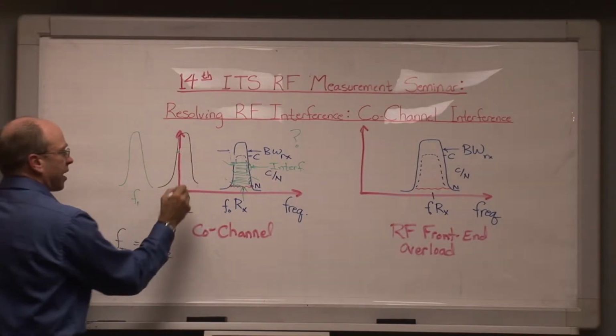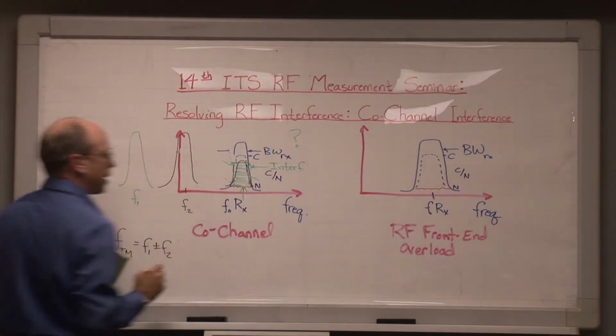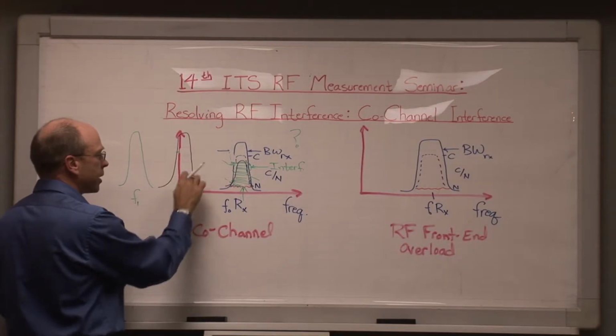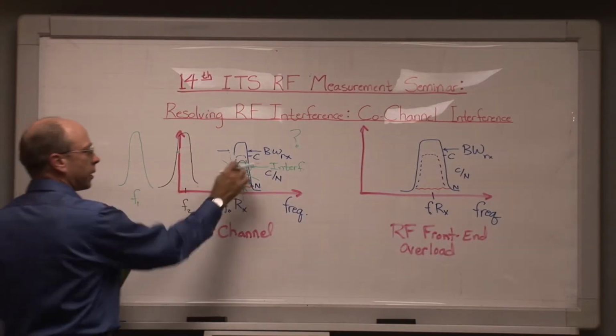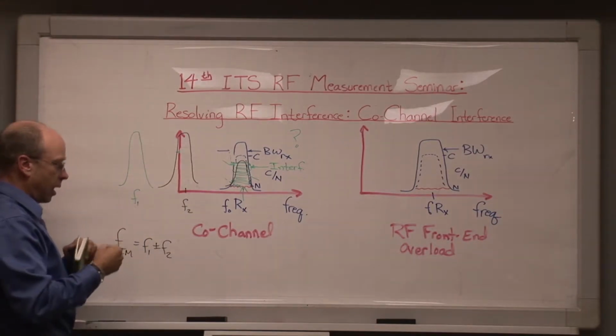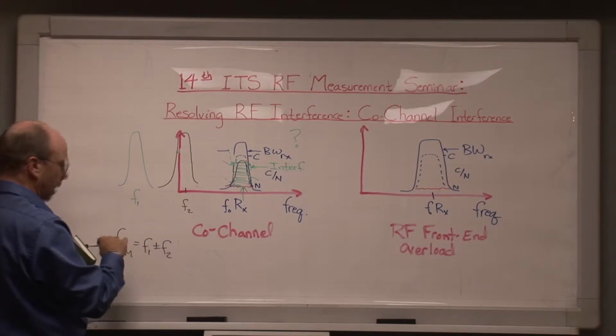The interesting thing in that case being that although this intermodulation energy can occur on this channel, neither of these transmitters is itself creating energy in its sidebands or its unwanted emissions that are actually on that frequency, but the operation of these two together can do this. And we can also get this kind of problem, well, I'll leave it at that for the moment.